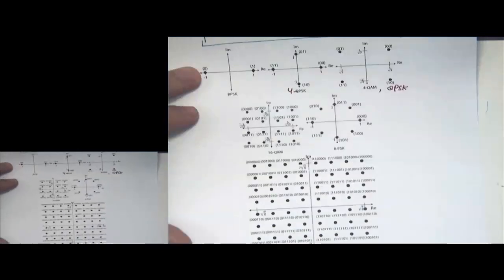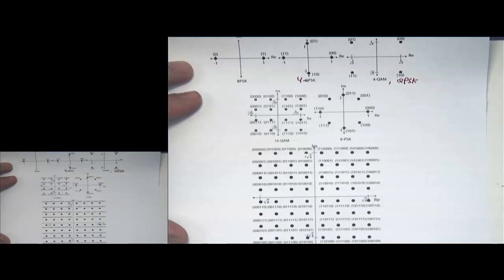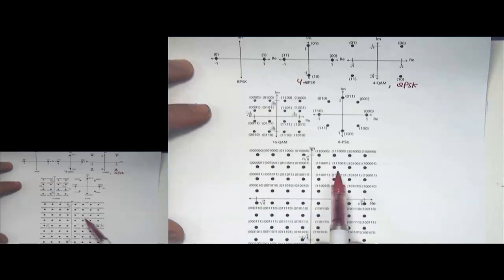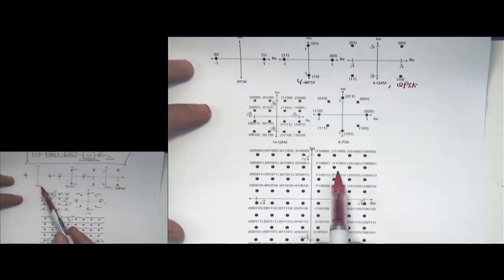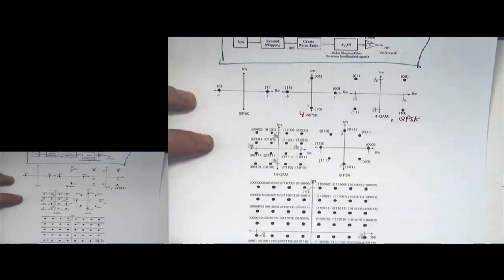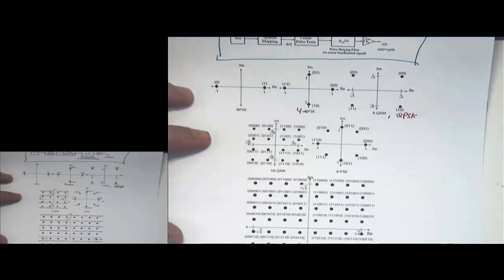So these are some constellation diagrams here. And sometimes the labeling can be different. So in a standard, they will actually tell you which the preferred labeling is. So all the labelings here for BPSK, QAM, 16QAM, 64QAM have come out of the 802.11 standard. And then the 8PSK one I got out of the EDGE GSM standard. Any questions about just this kind of bit labeling or these constellations here?